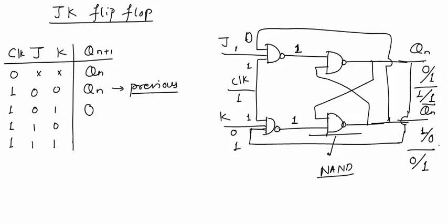So in both the assumptions, we obtained the next output as 1 0. Sorry, this will be 0. So in this case, if we assumed output 0 1, next output was 1 0. If we assumed output 1 0, next output was again 1 0. So whatever may be the output in the previous case, the next output will be 1 0. So Qn will have value 1 for 1 0 input. Now we'll see the next combination of input.